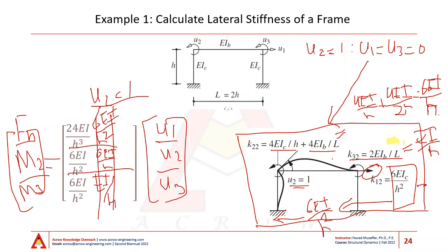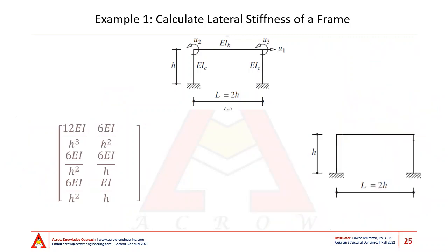In a similar way, we can proceed and fill the third column using my third free degree of freedom. What I'll need to do is rotate my top right node by a single radian rotation, and then this column would do this, and there will be a point of inflection over here. Please don't go into the curvatures of things that I'm drawing, because it's not going to look like what I actually mean, because I'm really struggling to draw on the screen.